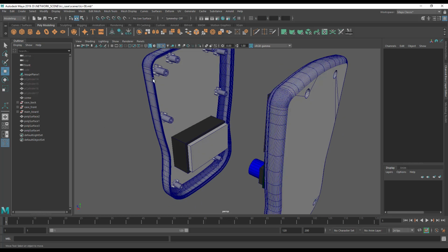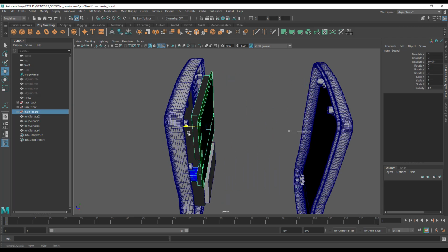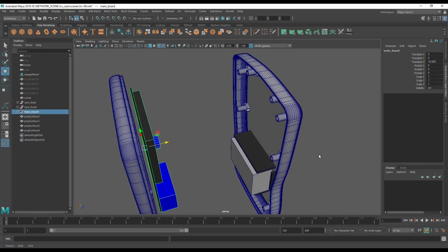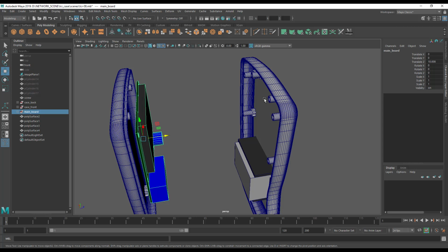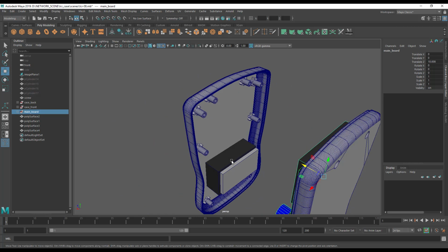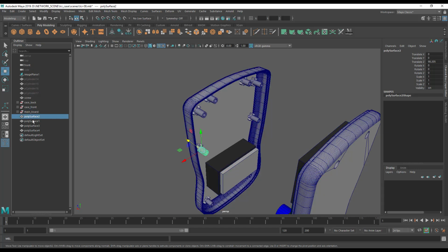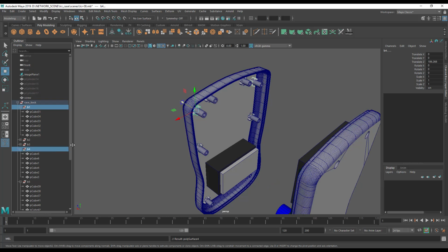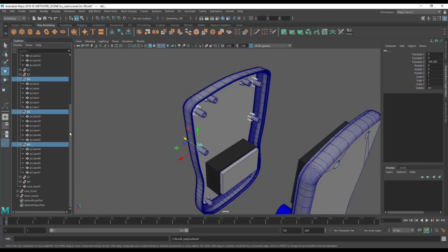Let's go ahead and do that, and we're going to have to adjust the size of these pillars. So our whole main board group, let's bring it down, and actually we know that it's in the right place right now. An easy way to do this would be to join the case halves together again. I can't do that at the moment because if I select the case front, you'll see this stuff doesn't select. So let's put all this in the case front, and then we need to move those support pillars from one to the other. So B1, B4, B5 and B6, we need to move them from the case back to the case front.